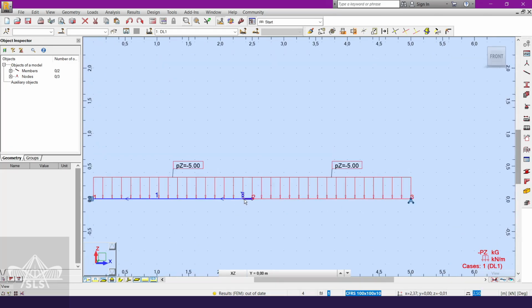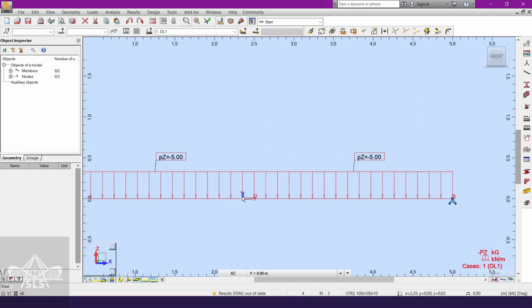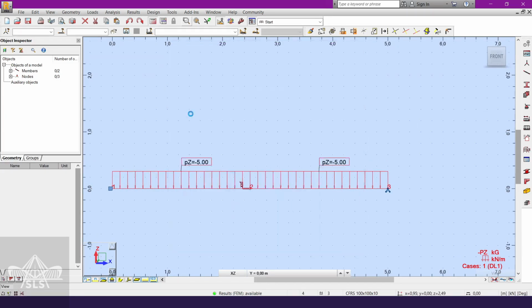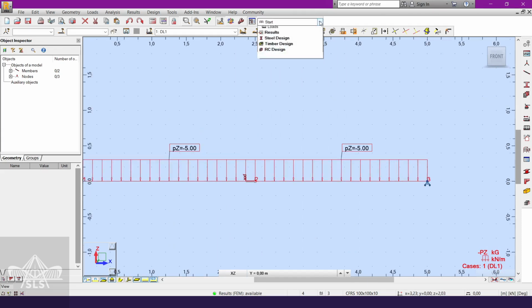But also, if you want to show how or what is released or not, we can turn this on. With this axis mean that they are not free to move, but for F it means that it's free, which is the third coordinate, which is going to be the rotation, and as we want here at the hinge to not have any bending moments, which basically is free to rotate. So now we successfully modeled the beam, so now we hit calculate.